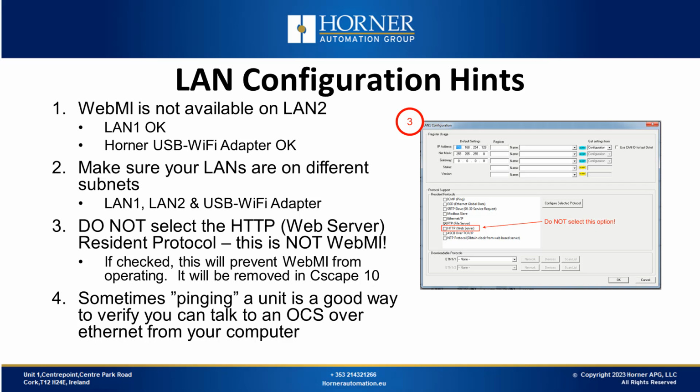And lastly, if you're not sure, you can communicate to the unit from your web browser. A good thing to do is to ping a unit just to make sure that you can actually communicate between your computer and the OCS itself over the Ethernet connection.